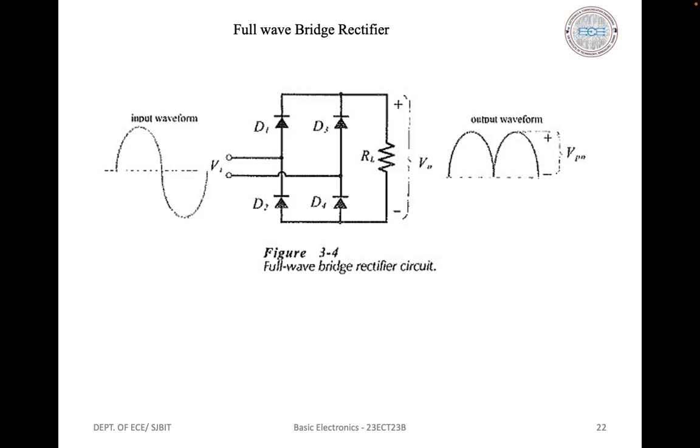Once again, it should be noted that most rectifier circuits use a reservoir capacitor to smooth the rectified voltage wave into direct voltage, and the presence of the capacitor changes the output waveform and substantially affects the load current and voltage and the diode current and voltage.